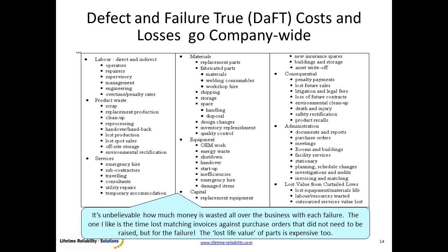I can repair a breakdown and have a maintenance cost for that repair, a direct maintenance cost: materials, labour, supervision. So I can cost that as a maintenance value quite easily. What I can't cost is everything else the company lost or paid for that there is no value to show. That's the value we have to use in our risk costing assessment.